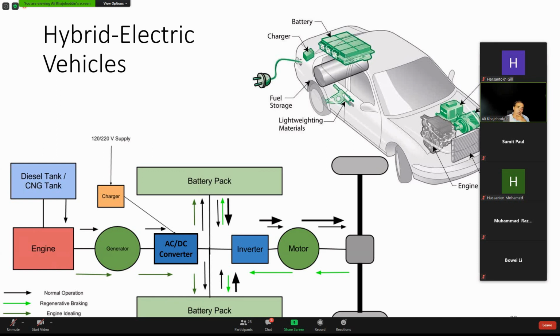And the EV mode, that was the one that I was looking for. In EV mode is when you don't have the gas, you can only take the power from the battery. So let's say the gas is done, so you get the power from there through the inverter, and then through the motor you drive the car. So you can see that you're managing the power flow, right?